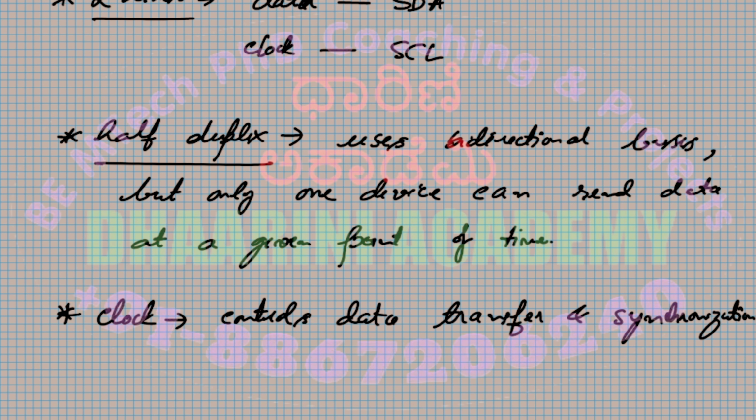So it's understood by now that there is only one clock, and every device that gets connected to this I2C bus, in the sense these two lines, will share the same clock signal. Later on, when we go to any higher level problem, you will see that normally the master is the one responsible for generating the clock signal.